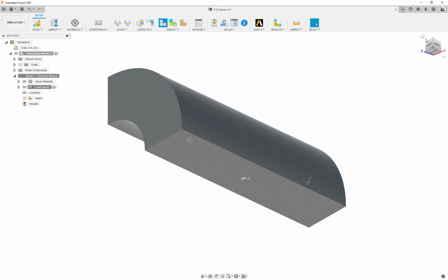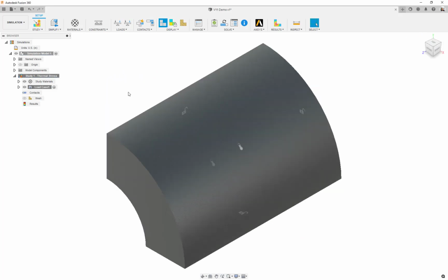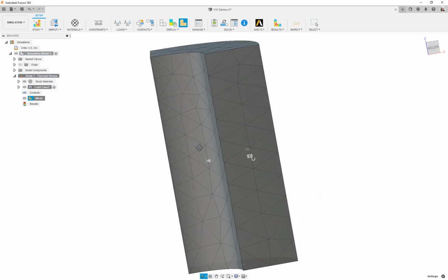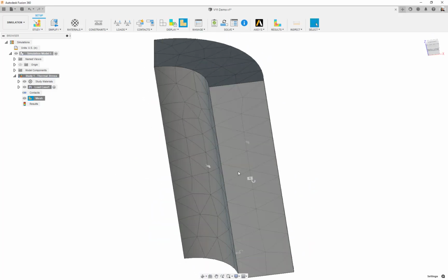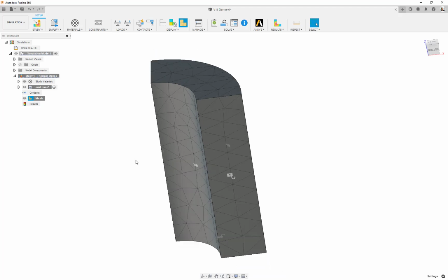All right, so let's go ahead and generate the mesh. I'm going to right-click there and say Generate Mesh, and you'll see here why we're going to go with a finer mesh. You can see the default's pretty coarse for this geometry. We only get 2 elements through the thickness, which when we're looking at a temperature gradient through the model, basically what is causing the stress in our model and displacements in our model, it would be good to have a few elements through the thickness.